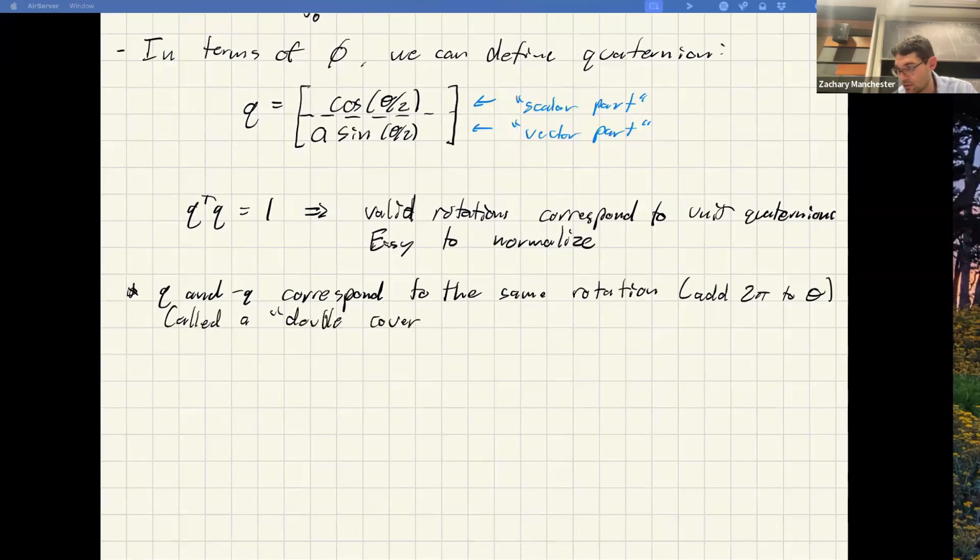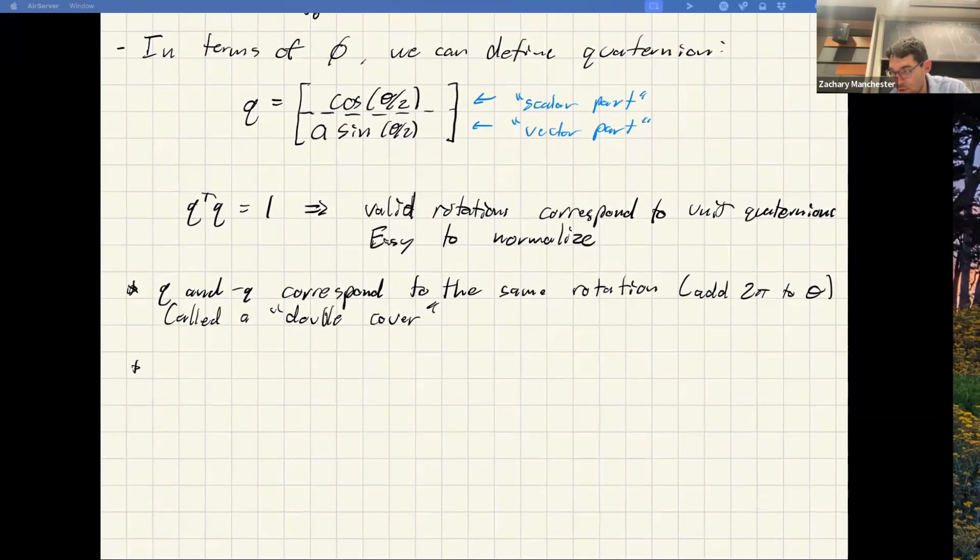And you have to sometimes be a little careful. So quaternions, unit quaternions, the full thing is they double cover SO(3). That means there's two quaternions for every rotation matrix. Let's see. So yeah, and the next thing to say here, which we'll now run down a whole bunch of, is that in most cases you can think of a quaternion like a rotation matrix, and there's a bunch of equivalent operations, and they basically work the same way.